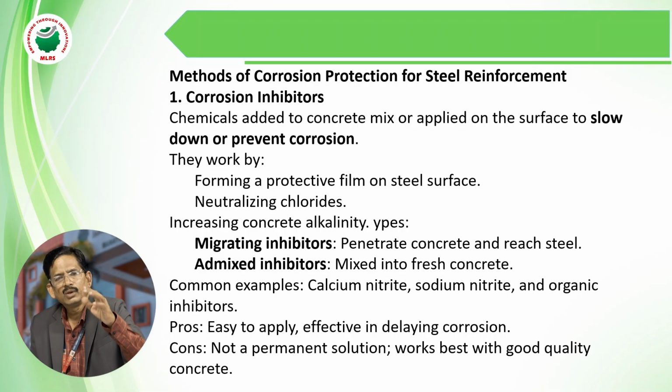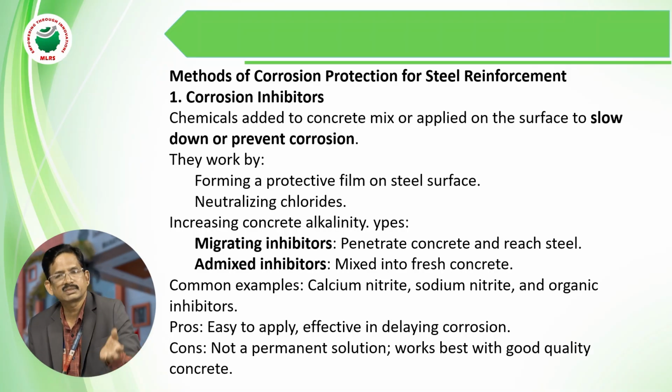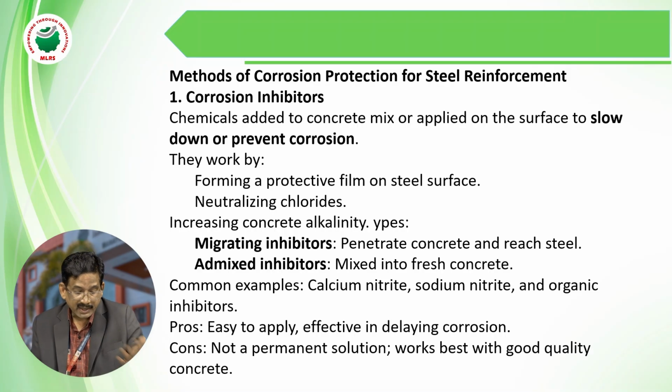I can't say that we can reduce it to zero, we have to reduce it to a certain minimum. So instead of 50%, if you reduce it to 40% also, it will be safe up to a certain extent. That's why these are called corrosion inhibitors. These are already available in the market. Admixed inhibitors also. Whatever concrete we are going to use, with additives or admixtures or retarders, in the similar way, for prevention of corrosion of the reinforcement we are using migrating inhibitors and admixed inhibitors also.